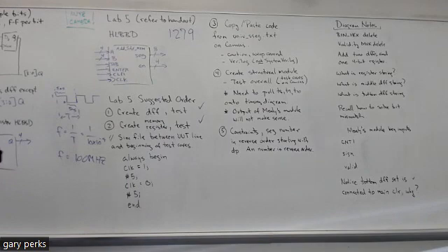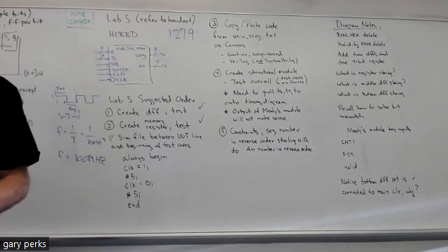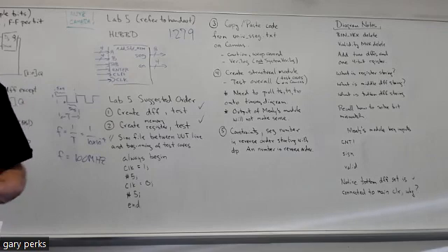You'll know if your memory is working when the switches change. Say you have it loaded onto your Basys board. If your memory is working, as you change the switches to a new test case, the display should show the old result until you hit the enter button with a different couple of numbers that you're either adding or subtracting. If you're moving the switches and your numbers are changing on the display, that means your memory is not working.